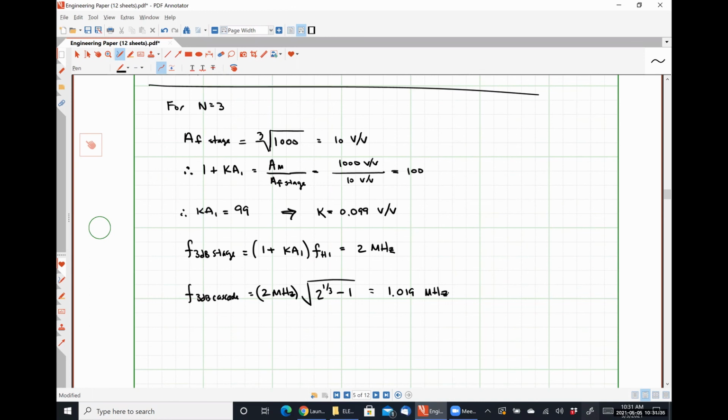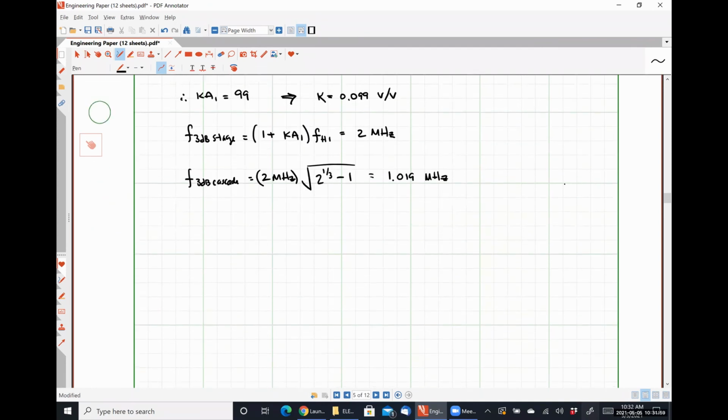Yeah, and then you have to do an iterative process. You either got it right, or if you overshot it, you would go down in the number of stages. If you undershot it, you would increase the number of stages. But all the math that we did here is dependent on all of the gain stages being identical. Okay. So this situation, just to be clear here,